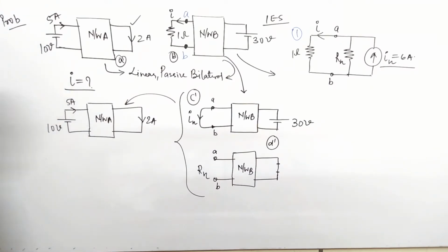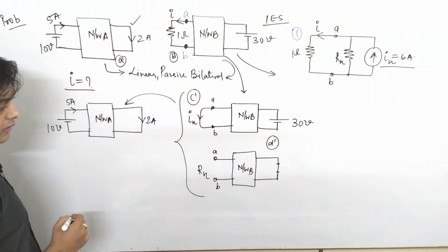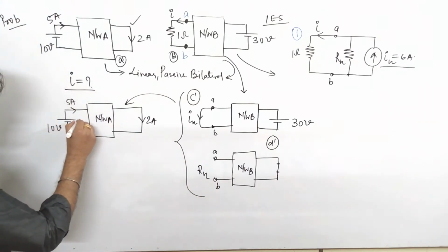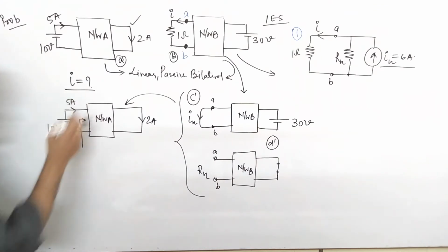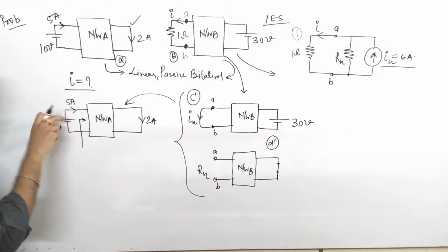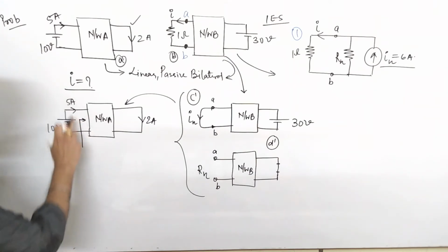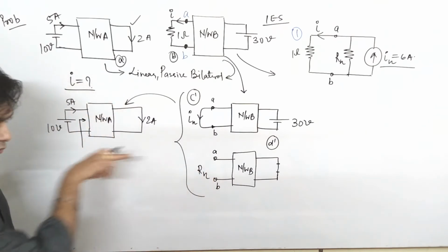For finding out the value of Rn, you see this is your short circuit branch. If you see these two networks, what should be the value of Rn here? What should be the value of this resistance so that this condition is satisfied? Just try to understand what should be the resistance across this terminal. This is basically known as a port resistance, and this port resistance is basically your Norton resistance looking at this terminal.